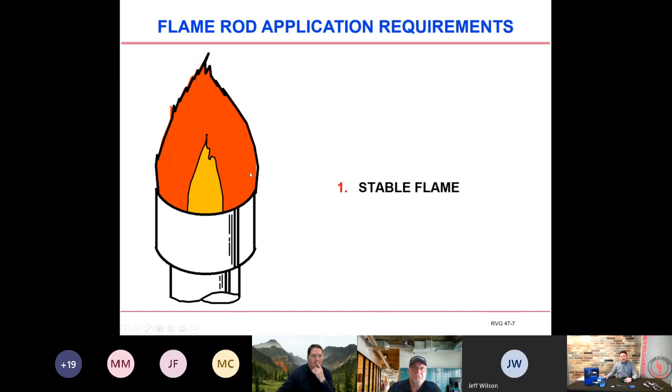The other thing that will add some complexity to getting this flame signal at a good solid reading would be if you get soot, or if you have any moisture or any type of buildup on the flame rod itself. When you get soot built up on the flame rod, it actually starts adding insulation and starts to change that 4 to 1 ground ratio.